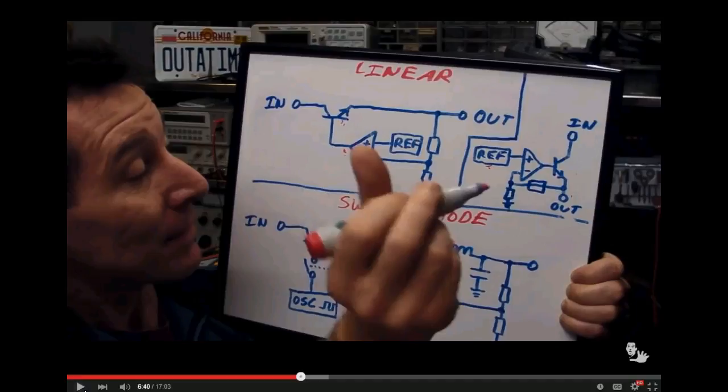It's a really neat device. These op amps are really, really sweet. So what he's saying is that, okay, we're putting 5 volts in right here, and it's going to try to make this be at what? 5 volts. If the output tries to go down, then they don't match, and the output will go up to get that feedback. And what he said is the only difference between this and the LM317 is that the voltage divider is outside. Here the voltage divider is inside.